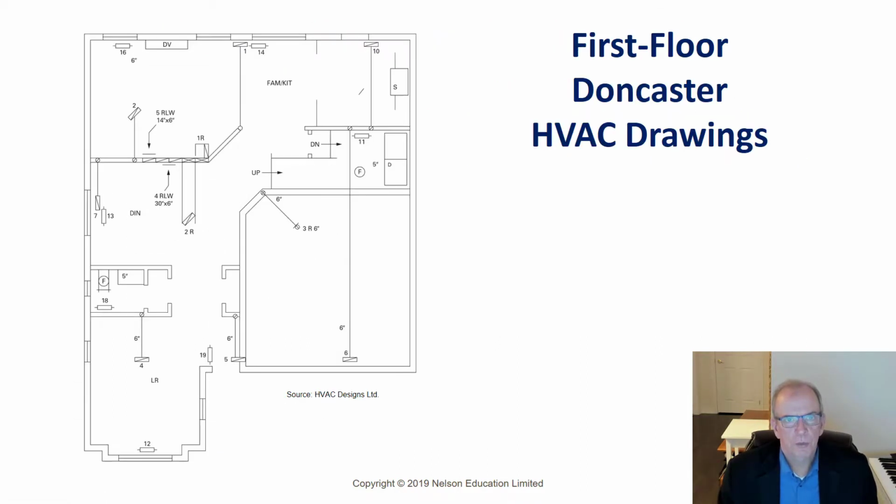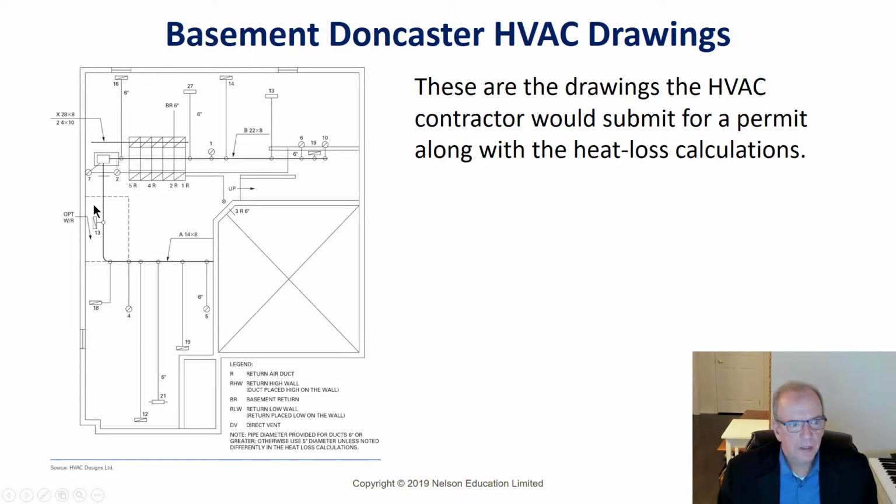It doesn't work very well with the system. So then basically our duct supply, and this is also saying the size of the duct. So it's a 6-inch duct. It's a 4-inch duct. It's a smaller one in this particular case. And when you see the line going through, that means it's coming out through the top. Where you don't see a line, that's coming in the ceiling.